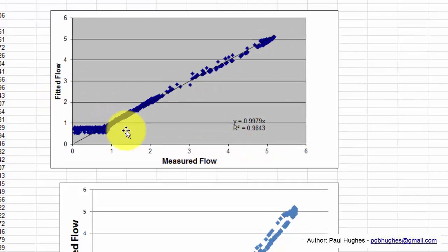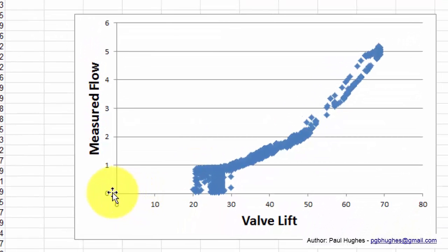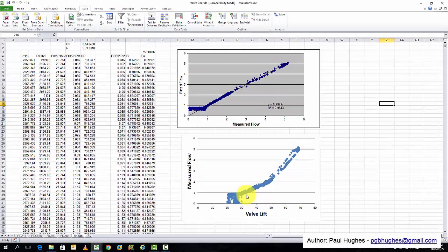So it's a very, very good curve fit, which means we now have an equation which can determine or estimate the flow in this region over here if we know the dP over the valve and the valve lift at that time. Here's the characteristic, or here's the solved value is 0.5 as theoretical, well, CV, artificial CV, and R being 9.7 shows that it's a strongly equal percentage valve.